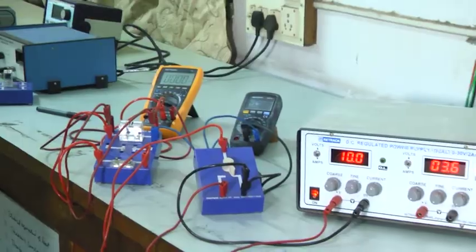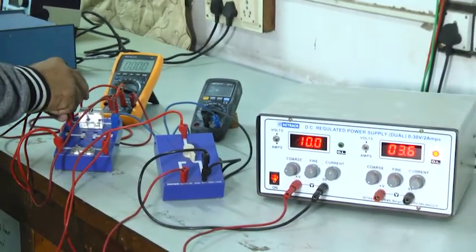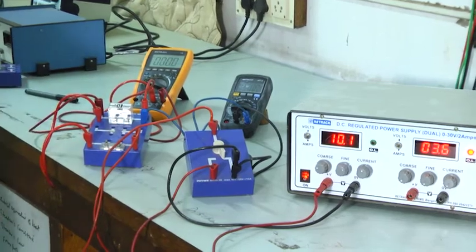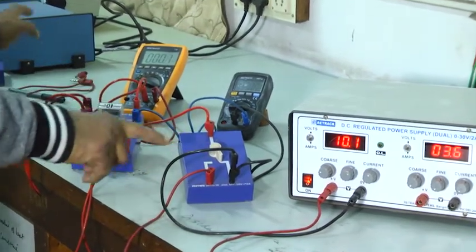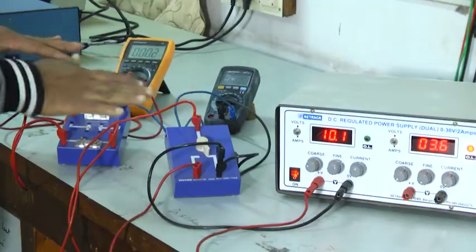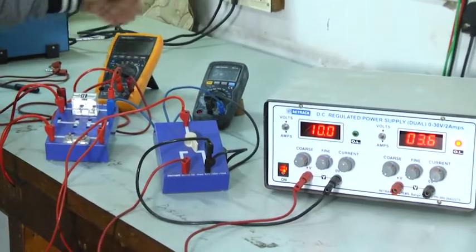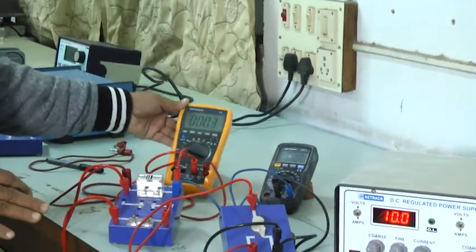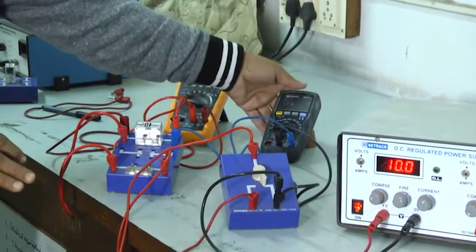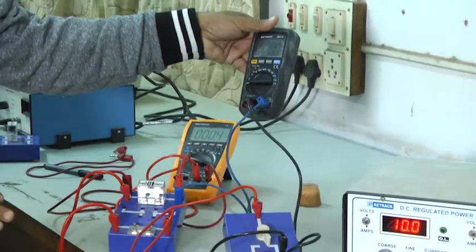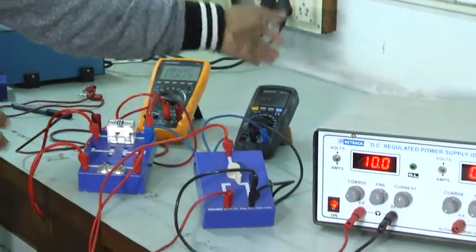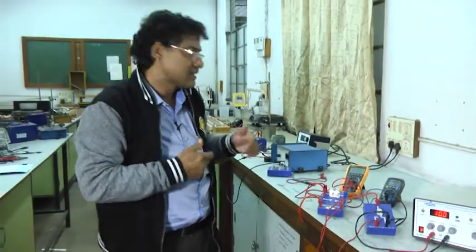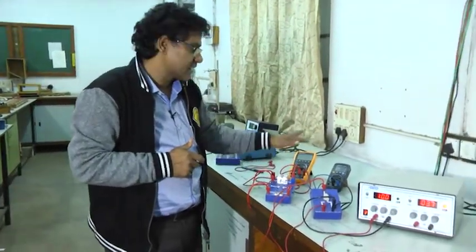So it is in discharge mode, okay. Now there is no charge in the capacitor, so that is why the reading is, you see, almost 0, right. It is 0.3 millivolt, and the current in the circuit is 0. Now we have to note down at t equal to 0 what the voltage is and what the current is.